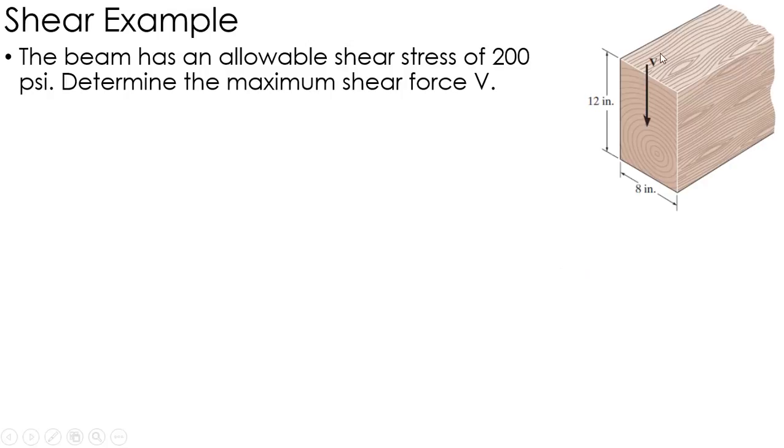Okay, in this problem I've got a beam over here, a wooden beam. It has an allowable shear stress of 200 psi, and I want to figure out what the maximum shear force it can handle would be. So again, we're going to use the equation VQ over IT.